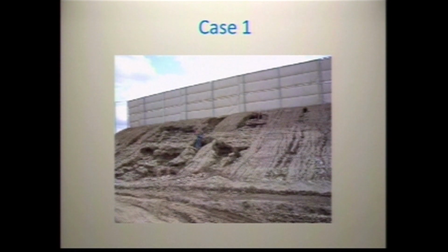Yeah, there's flow coming over the top of the slope. It's a huge problem. Something that the QSD was probably asleep at the switch on. You can't have uncontrolled flow over a 2-to-1 slope, or you're going to get gullying exactly like you see in this picture. So that needs to be regraded so that the water goes away from the top of the slope. Absolutely right. How about?